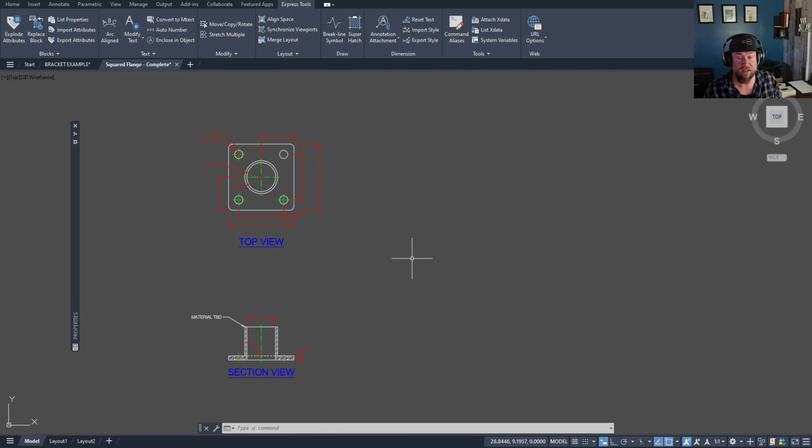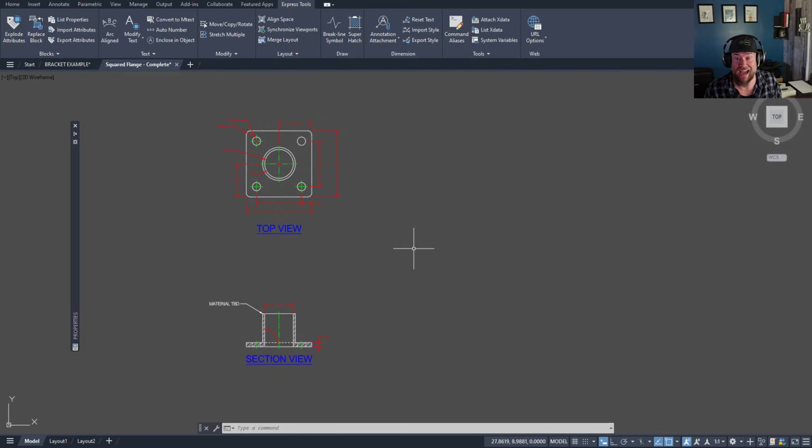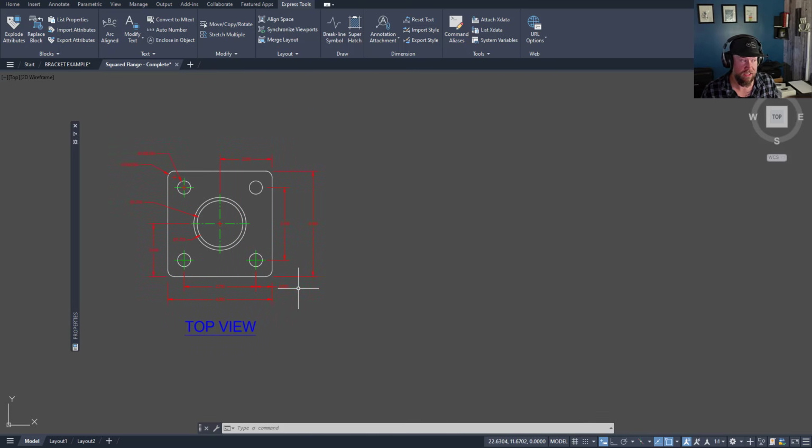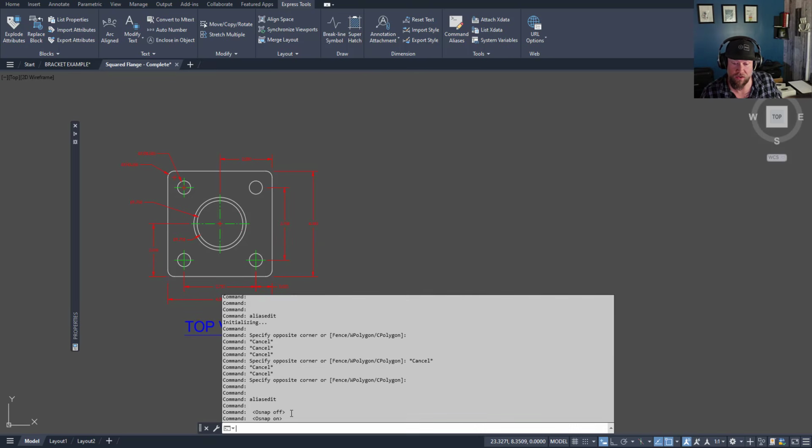Next up, in the same way, I want to make sure that everybody knows a ton of the shortcuts or quick commands that are going to activate settings for you within AutoCAD. Now, I'm constantly using a few, and some of those are the F3 command. So if you tap F3, you can see it turned my OSNAP or object snapping off. If you tap it again, it's going to turn it on.